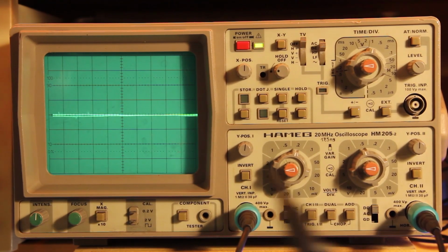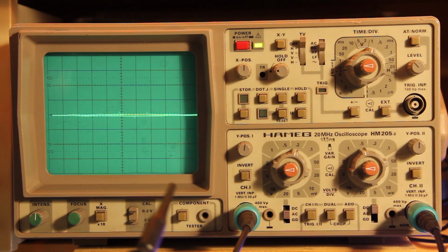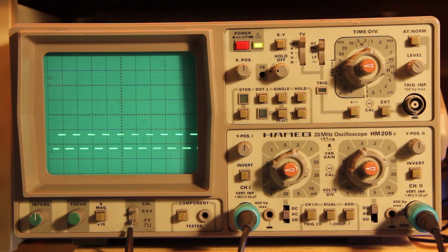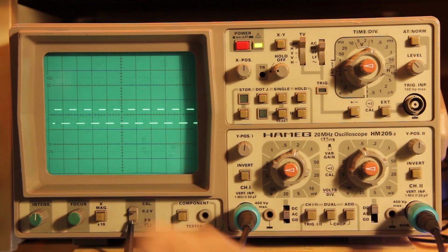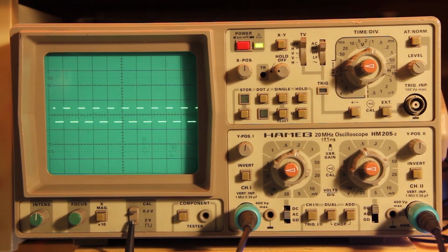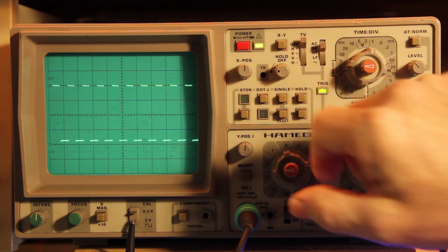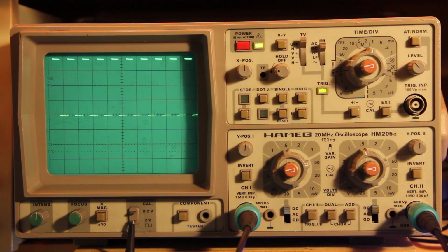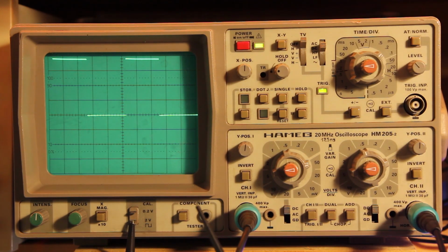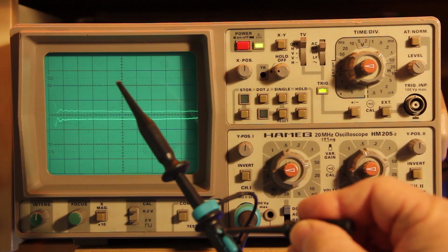Now, before starting operations with the oscilloscope, it's important to adjust the calibration of the probes. This protruding grommet is an output specifically designed for this purpose. The probe needs to be set for calibration as specified, typically switching to 1:1 or 1:10 attenuation if it is a dual attenuated probe, and set the input for DC and adjust the amplitude to cover the full upper screen. Also set the time base to display some cycles. Then with a special screwdriver provided with the probe, adjust this trimmer screw.